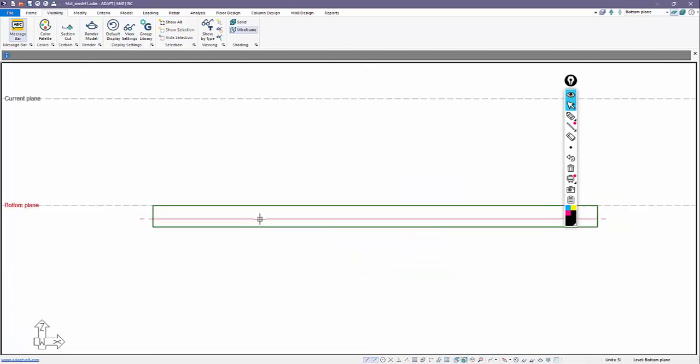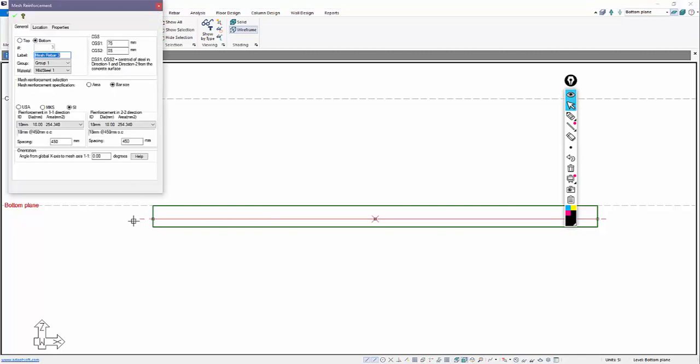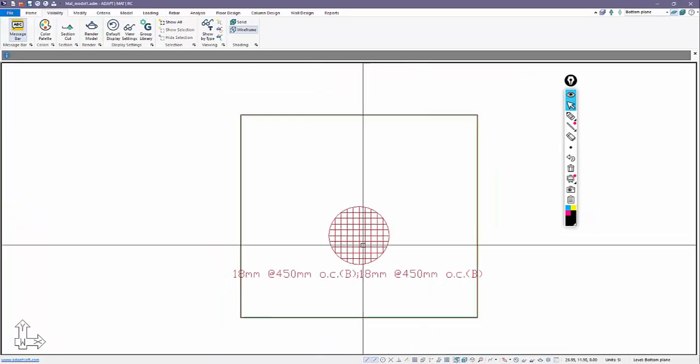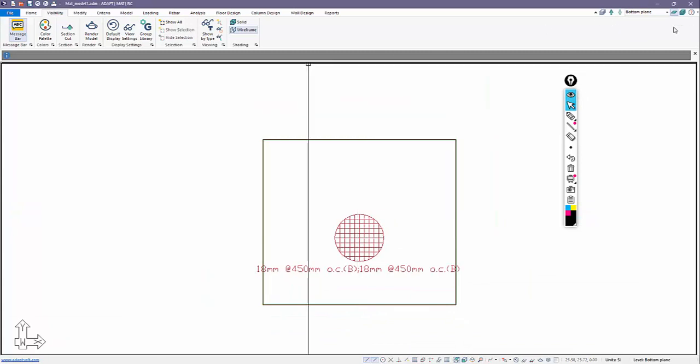Now this is still referenced off of the upper slab. The upper slab is 150 millimeters less than this thicker slab. So I need to adjust these by 150 millimeters. And here we're going to set this then to 225 and 235. And it should be negative actually. So if we have 75, 150, this should be negative 75, I'm sorry, and negative 85 because we're going downward. Like so, okay? And that's how we obtain the proper depth of the reinforcement within that zone.